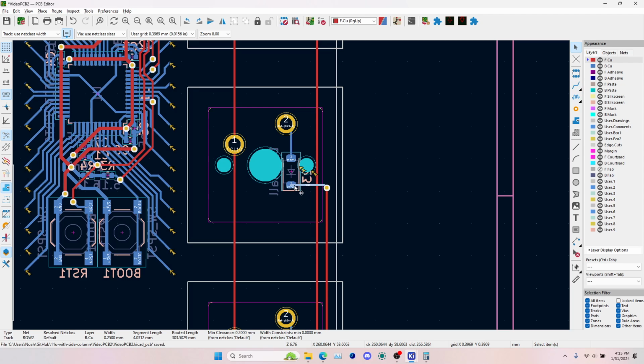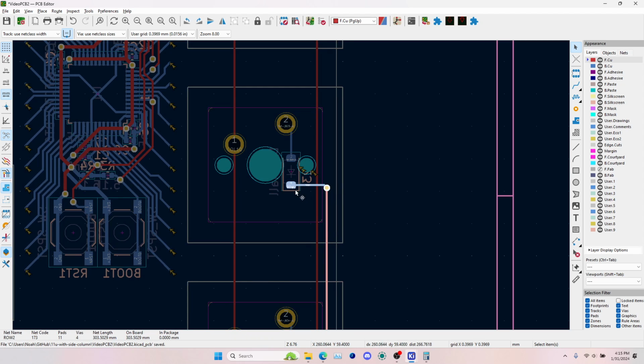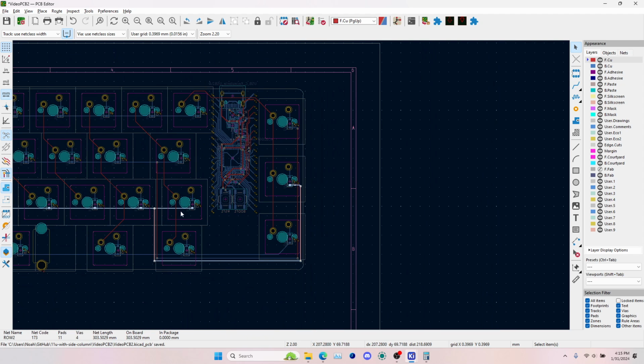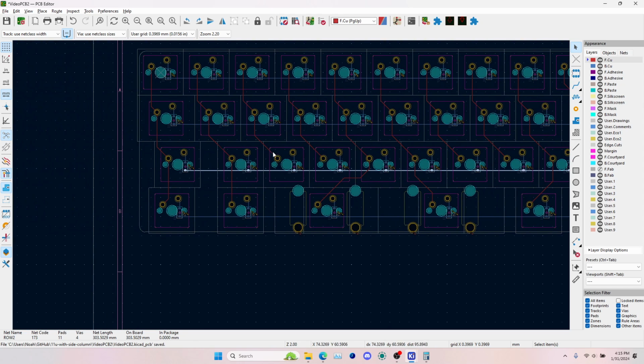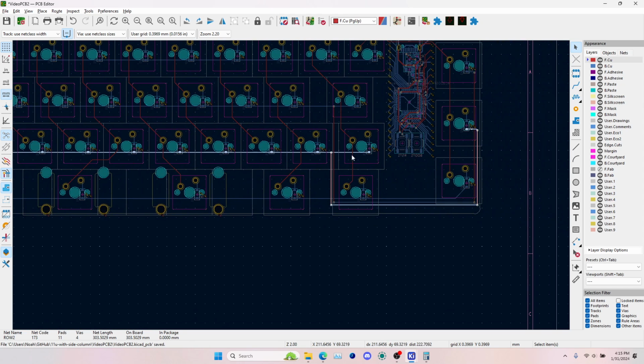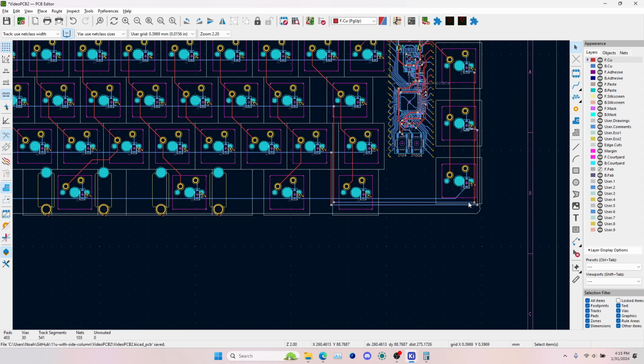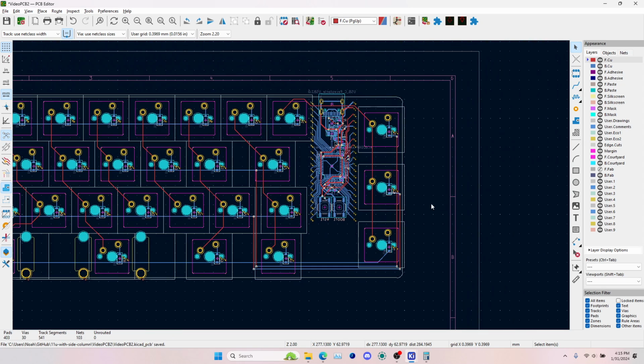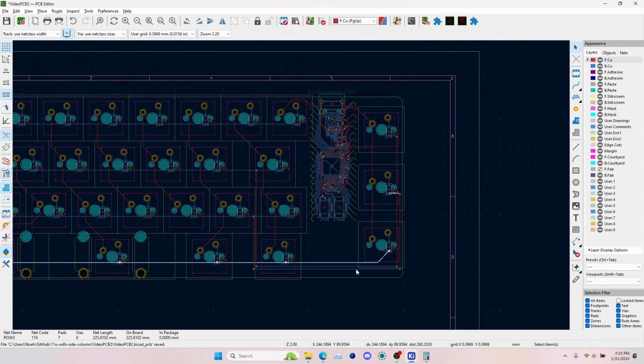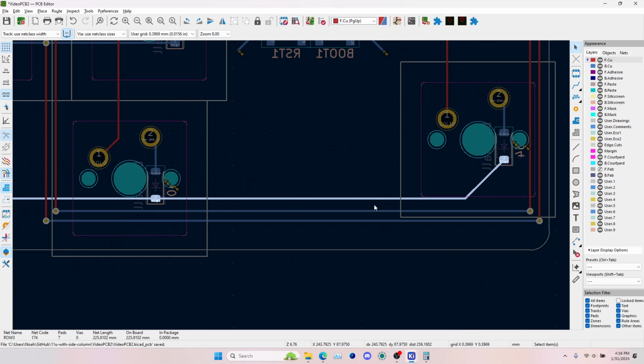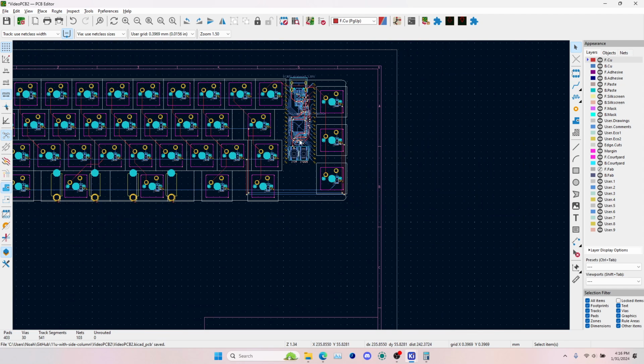So now this row trace, if I hit tilde or back quote, top left of your keyboard, that row trace, row 2, goes across all the switches and then jumps down and jumps back up to get that last one. Same for row 1 here. Row 3 you could just go across because, well, there's nothing stopping it. Nothing in the way. So the next thing to do is to grab a bunch of I/O and just shove it over to the matrix columns and rows.